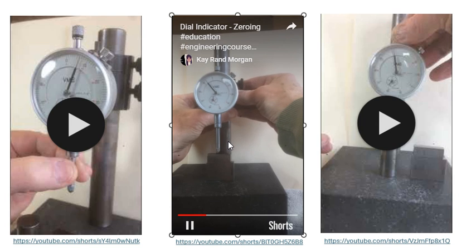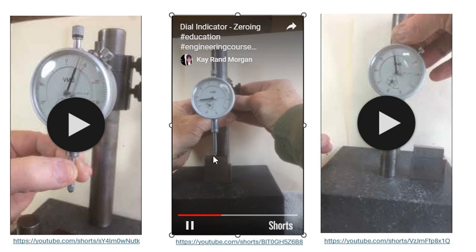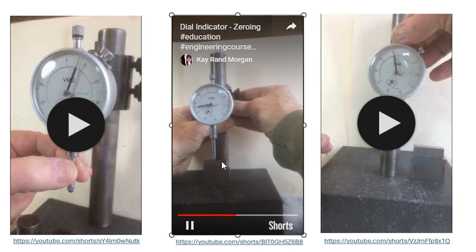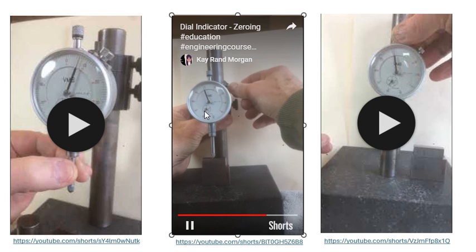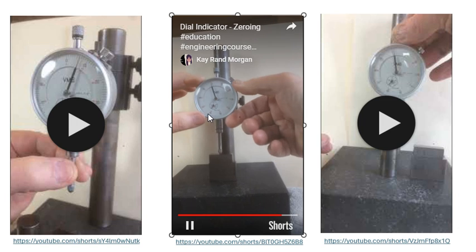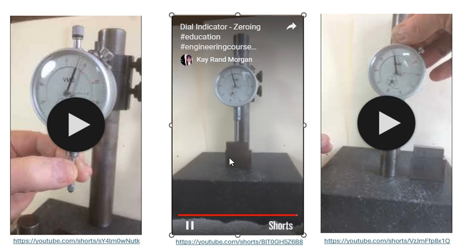As we bring this down, look at this. The dial is going to start going as soon as our contact touches the surface of this gauge block. And as you do it, you have to make sure that you pay attention to how many turns it went in this little dial. Then we're going to adjust the screw right here so that we can set the pointer at 0.